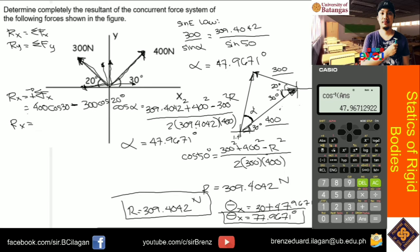So 400 cosine 30, let's just use the calculator. 400 cosine 30 minus 300 cosine 20. So that is 64.5024 Newton.